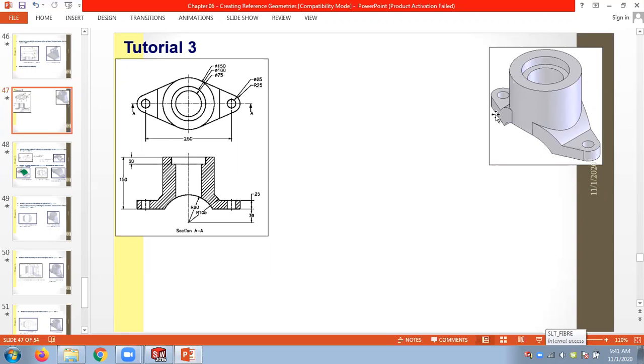We have to have this shape first drawn, and draw the cylinders in a plane and extrude to the surface, because this is a curve, you cannot draw anything here. Everything we have learned here is needed now. So we have to draw only the areas we can extrude first. We can extrude this area only, without the cylinders.